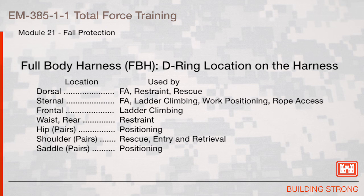Full body harness D-ring location on the harnesses. D-rings can be located in many positions on the harness. The dorsal D-ring is used in fall arrest, restraint, and rescue. The sternal D-ring is used in fall arrest, ladder climbing, work positioning, and rope access. The frontal D-ring is used for ladder climbing.